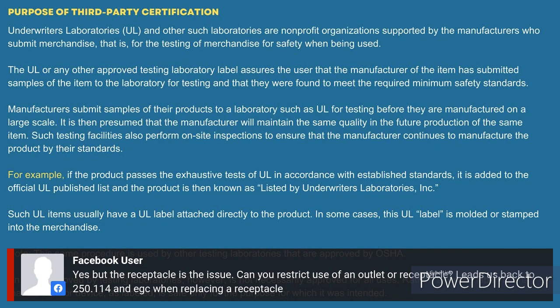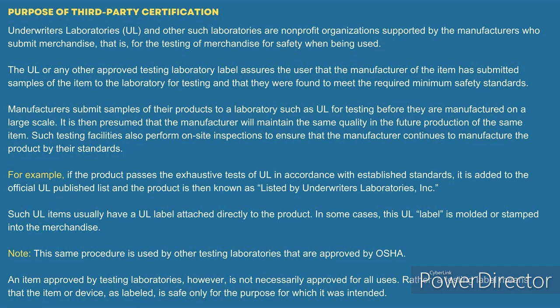Can you restrict the use of an outlet or receptacle? Leads us back to when replacing a receptacle. I'm not sure exactly what he's asking there. The receptacle is a device. The box is the outlet. So if you're looking at the receptacle and saying you need GFCI, I'm assuming that you went out there and had a device and there was no equipment ground out there. Is that what you're asking?